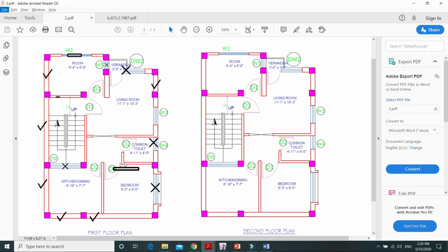Apply and OK. Here are some walls, for example this partition wall which rests on the slab. The load applied by the partition wall which rests on the slab is converted into kilonewton per meter square. That is, we calculate the total load, that is unit weight of masonry into height into width into length of the masonry wall, and then we divide it by this panel of slab and we apply this load to this slab. Just for the example, I am calculating this load and applying it to this slab.